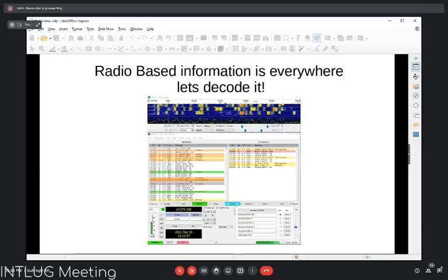And this has very high, what they call noise immunity, or signal to noise. You can operate with very low signal to noise, actually below the noise. So if you're listening to this, you may not hear a given signal, but there could be something like 20, 30 decibels, and that would be between 100 and 1,000 times quieter than the noise. So very low signals can be picked up and dealt with digitally, and you're not deafened by the noise as you're going through.